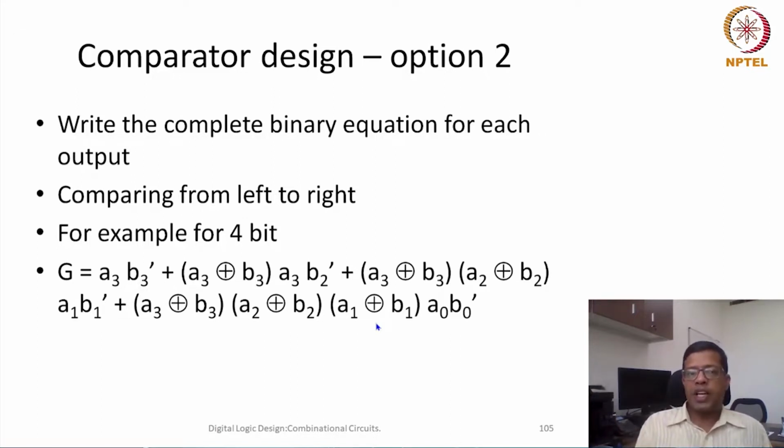Okay, and our latency, as we have discussed in our previous classes, our latency or delay of the total circuit depends on the worst case path. So the idea is that we have to finally write all the equations till A_n to A0. For example, I have written one equation for 4 bit.